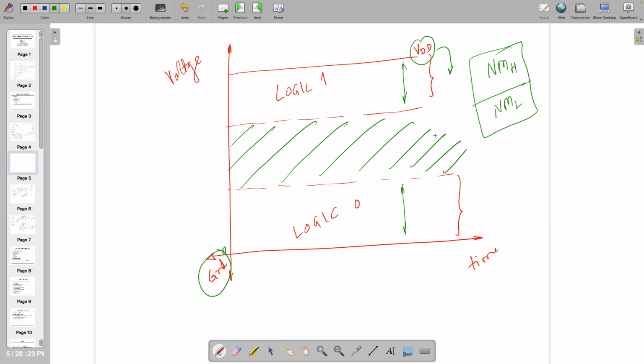And in that case, you might land up in the analog only. There is no other choice. You can't make everything with digital, or you have to do something at the analog level so that digital people can work it out properly. That's the problem, and that is the reason why we are not going below 0.9 volt. That's the voltage available with the TSMC 28 nanometer. We are using 0.9 volt, right?